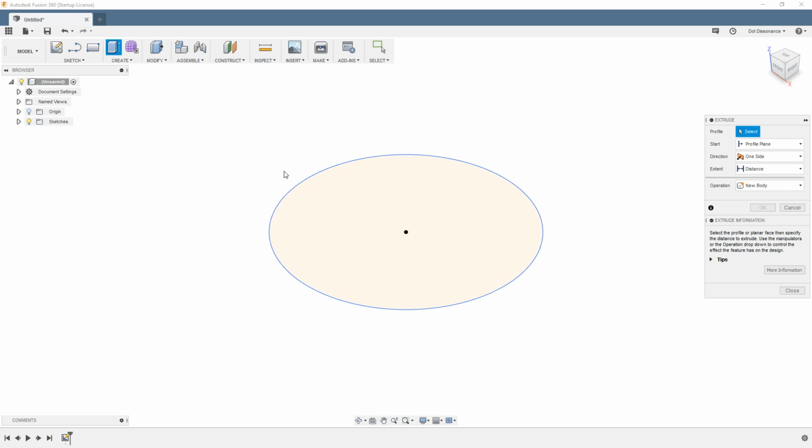But realize what really has happened in the two-dimensional environment is you did not create a disk. You created a circle. You created a string. And so if you're using CATIA, I believe it's been a bit since I've been doing SolidWorks, but I think it was the same way. You'd actually have to pick the edge of it to get the string.